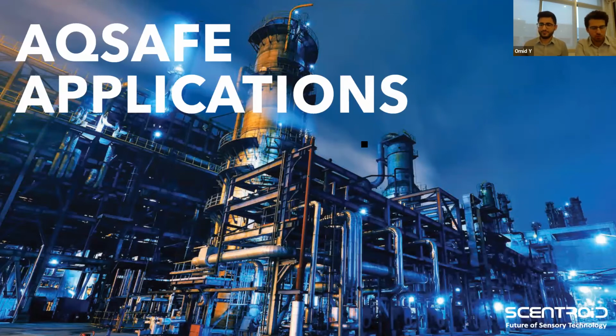For recalibration, we recommend another product that we have, the GD600, to simplify the calibration procedure. It'll allow you to do multi-point calibration on your sensors, and it'll even automate that for you. The next question is, could the device export data in micrograms per meter cube? So you're referring to the particulate matters, and the answer to that is yes.